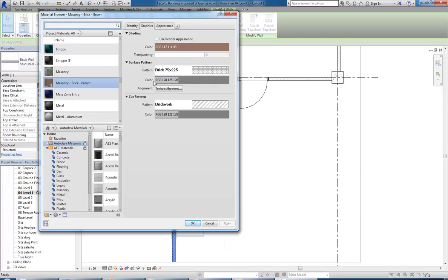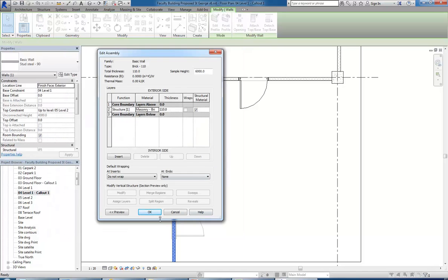Right, and again, once that's clear, it can make it a lot clearer what the colour here does. So the shading colour, obviously, is doing the fill in shaded views, but then the colour options here for the surface and the cut pattern do the colour for the pattern. But again, you can use that solid fill option in some cases if you want a solid material or a solid colour. And you can also use these in combination. So with the surface pattern set to grey there, just click OK.